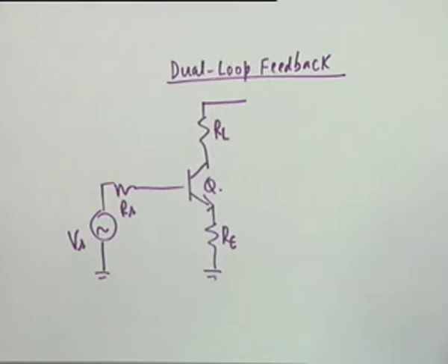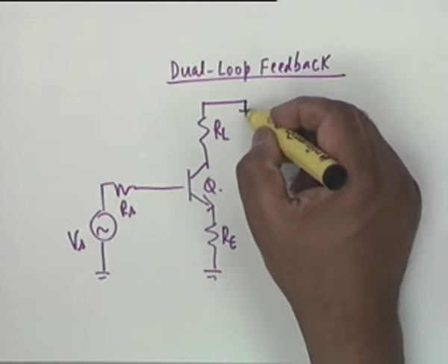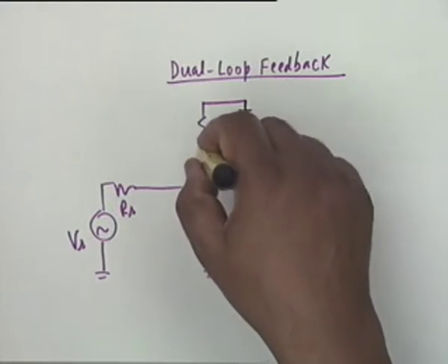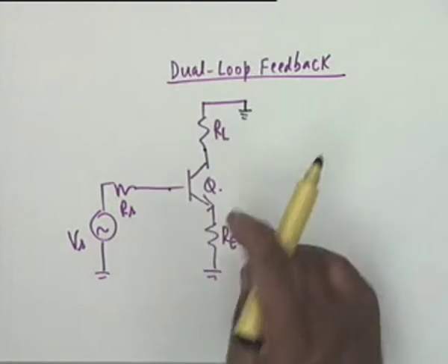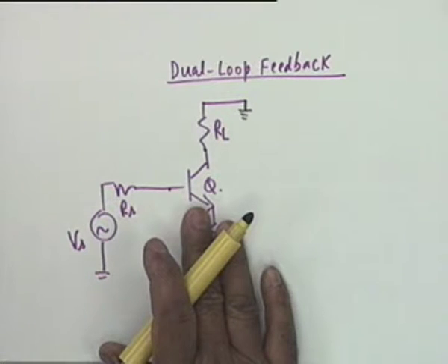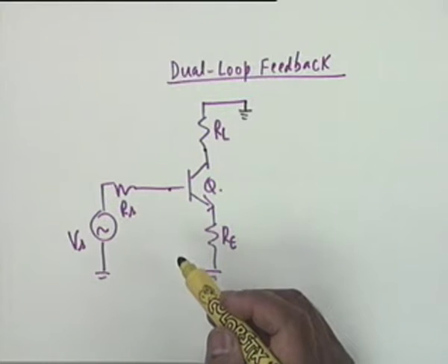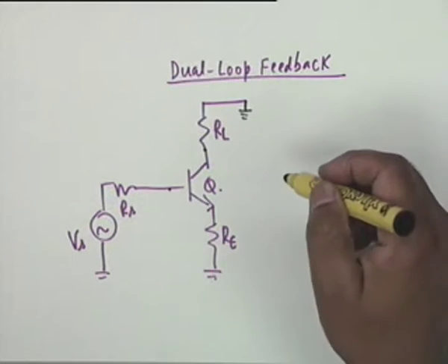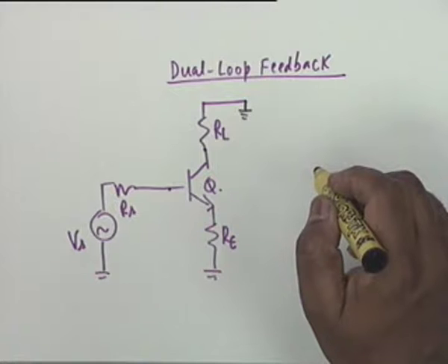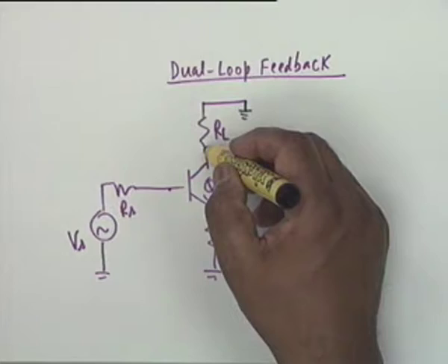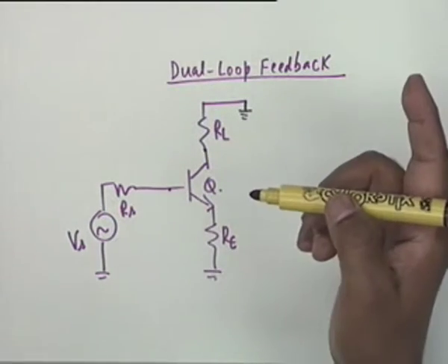Now, naturally the question arises, and in the shunt, what we had done was to connect a resistance from here to here, and RE was equal to 0. All right. Now, in this case, Ri is high and R0 is also high. Isn't that right? Okay. On the other hand, in the shunt, Ri was low, Ro was also low.